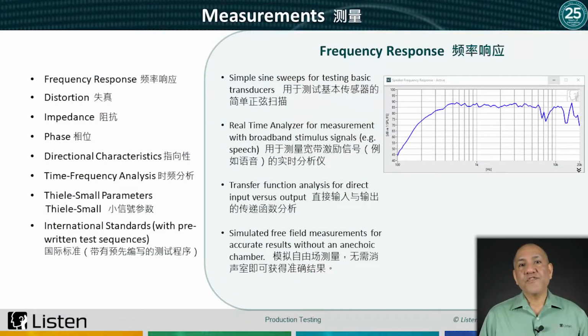Let's look at some electroacoustic measurements you can perform in SoundCheck. Everyone is familiar with frequency response, represented on an XY graph where the x-axis is frequency and the y-axis amplitude or level. The analysis is done by comparing the test stimulus to the recorded response. Usually you want a flat curve with minimal peaks and dips.